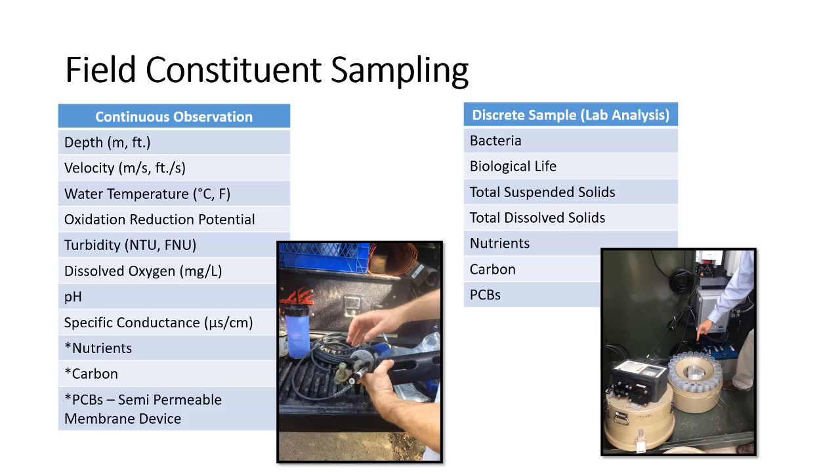Okay, the column over on the right-hand side are the various constituents that we would actually have to do some sort of physical sampling or physical characterization. You remember the biological methods where you're kicking around in the stream and actually counting the critters. The bacteria, you would have to feed and incubate over some specified time frame to grow them, and then maybe count the number of colonies that form on a little filter or something similar. But in any case, you can't really do that in the field, right?